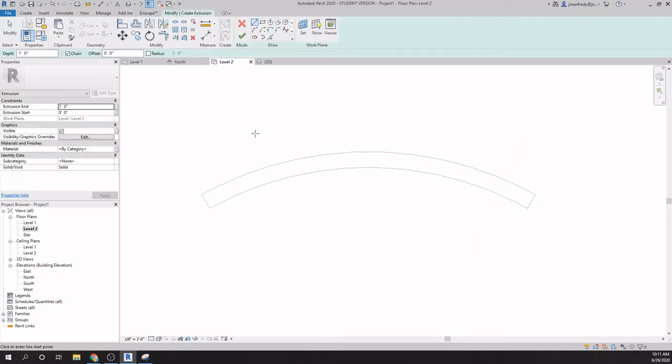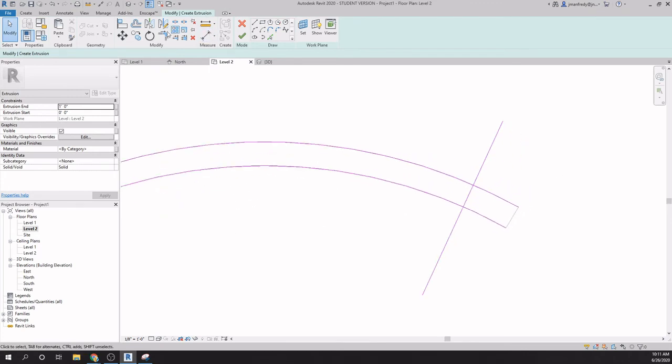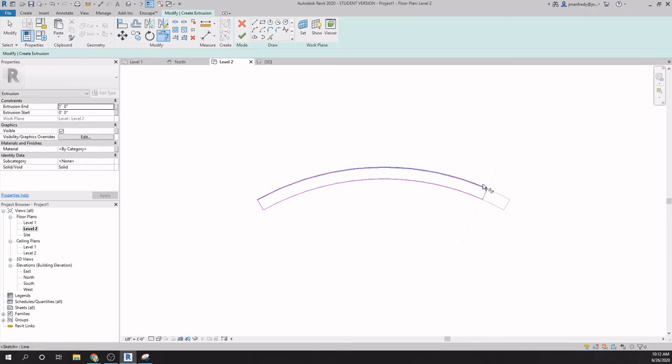So here's Extrude, and I'm going to trace this wall. I'll use the pick lines command, and I'll literally trace the wall. I'll pick this, I'll pick this, I'll pick that edge, and I'll pick here my reference plane. And then I hit escape to cancel out of that. And I'm going to trim these edges because I want a clean loop. So I'm going to type TR, which is right there, the trim command, and keep this and keep this. Keep this and keep this. And it cleans up the intersections. There. There's my loop.